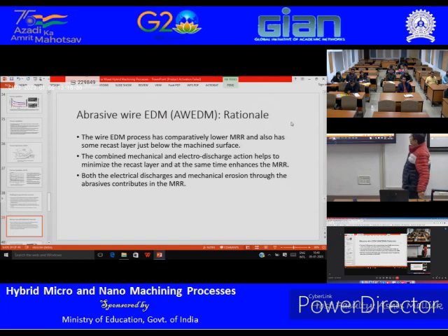Okay, so abrasive wire EDM, very similar. Instead of a tool, now you have, for example, zinc coated wire. When you are extruding the wire material, what you are doing is adding some abrasive particles there, right? So yesterday in the lab you saw the wire EDM, right? There is a wire material. Just consider that wire material is brass and very smooth.